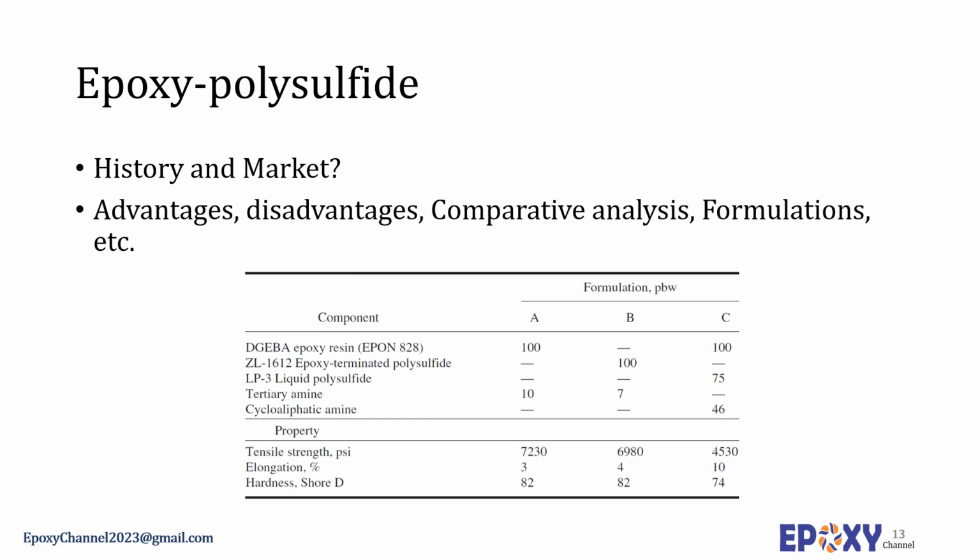Polysulfide resins combine with epoxy resins to provide adhesives and sealants with excellent flexibility and chemical resistance. These adhesives bond well to many different substrates. Tensile shear strain and elevated temperature properties are low. However, resistance to peel forces and low temperature is very good. Epoxy polysulfides have good adhesive properties down to -100 centigrade, and they stay flexible down to -65 centigrade.